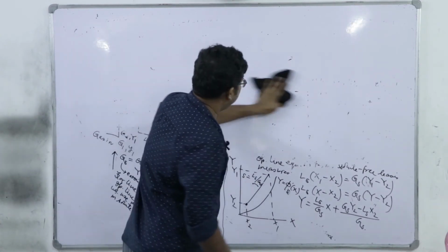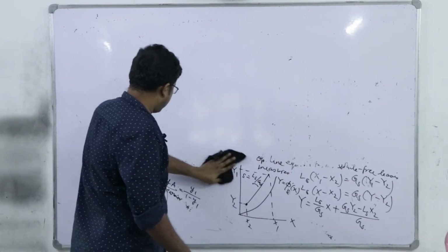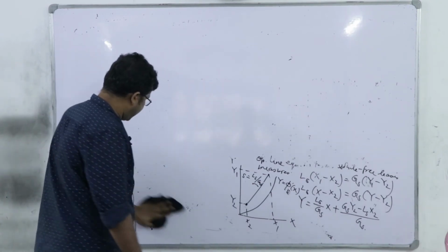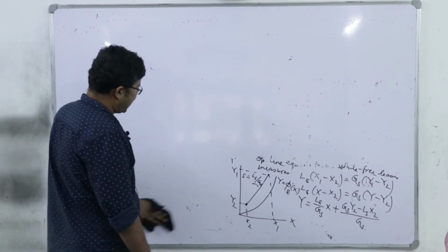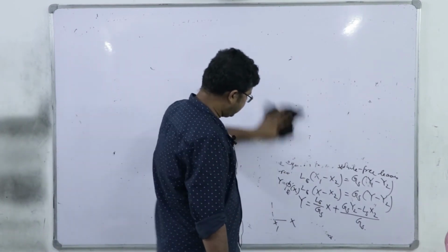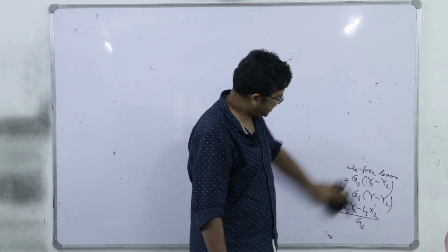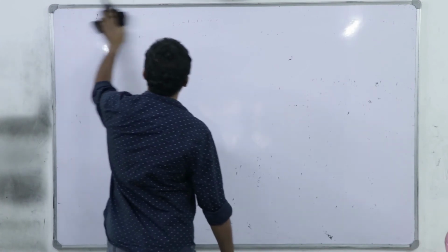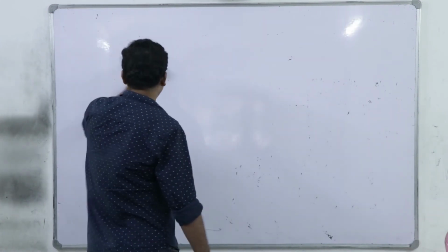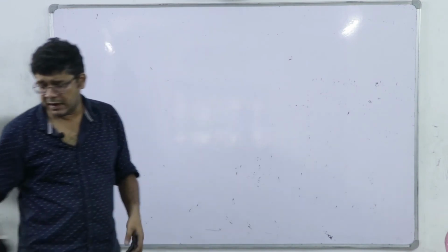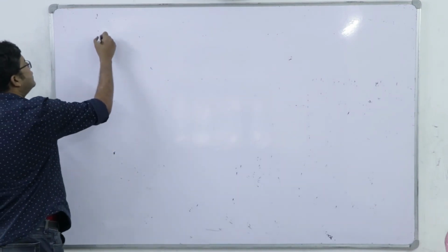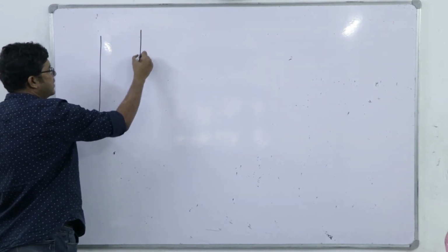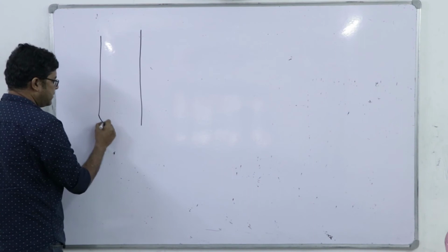So in a plate column, as I have mentioned earlier, we have a number of plates, which are trays that allow the contact of gas and liquid. The liquid is continuous where the gas is dispersed, and we must have an arrangement for the smooth delivery of liquid from one tray to another at its bottom. It's the typical schematic, not the engineering details we are discussing.